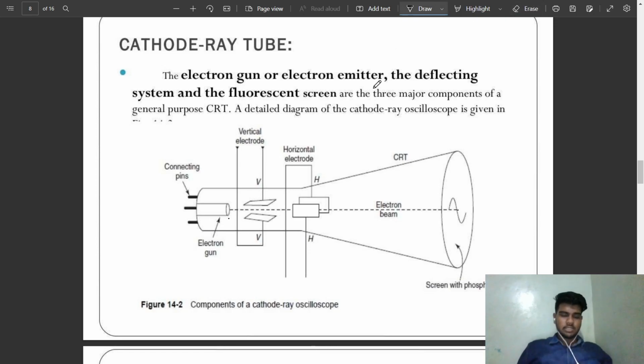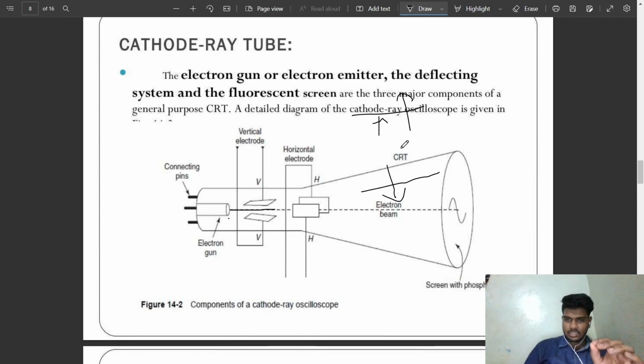Now, the electron beam from the electron gun, as a single point, is going through this vertical plate. The vertical plates are in this V. It is given a charge, which means it pulls the beam towards itself, the lower beam downward and the upper beam upward. Let this be a cross section, where it will be a single point. When the single point passes through the vertical amplifier, it becomes a line, which means only the amplitude of the signal is seen. Initially it had zero amplitude. Passing through the vertical amplifier, we are able to see the amplitude, which is the extent of its value.